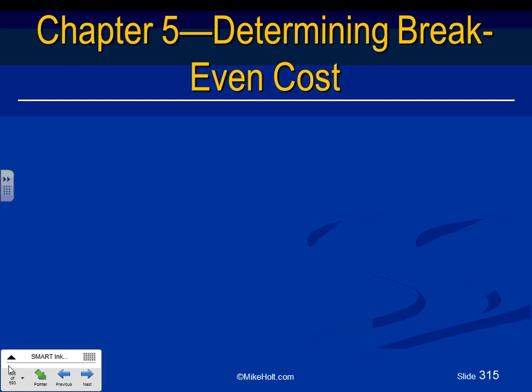And then we talked about the steps of estimating, guys. I'm going to go over the steps of estimating one more time. Step number one, understand the scope of work. Step number two is the takeoff, which you are doing right now for the commercial project, determining the bill of material. Luckily, in the software, guys, you're going to pull all this information directly from the software, the bill of material.